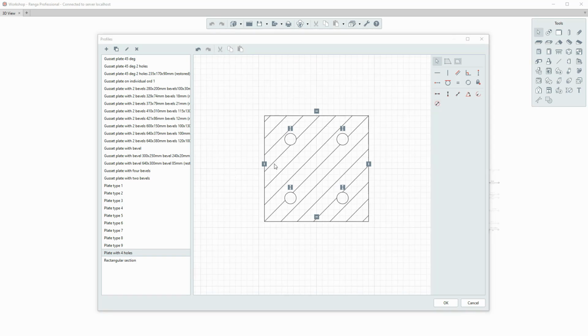To set the dimensional constraint, do the following: select the dimensional constraint that you want to apply. Using tips, specify the points between which the dimension will be determined. Then select the dimension using the Select tool. Now set the following parameters of dimensional constraint.